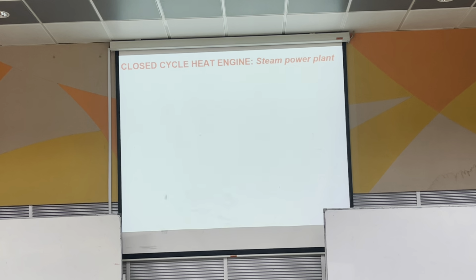So in a cycle, if we assume that there are no losses, energy in should equal energy out. So the energy in here will be work in plus Q in, then Q out plus work out. And logically speaking, we know Q in should be higher than Q out, work out should be higher than work in. That's why we end up with Q net in equals work net out, whichever one comes first, doesn't matter.